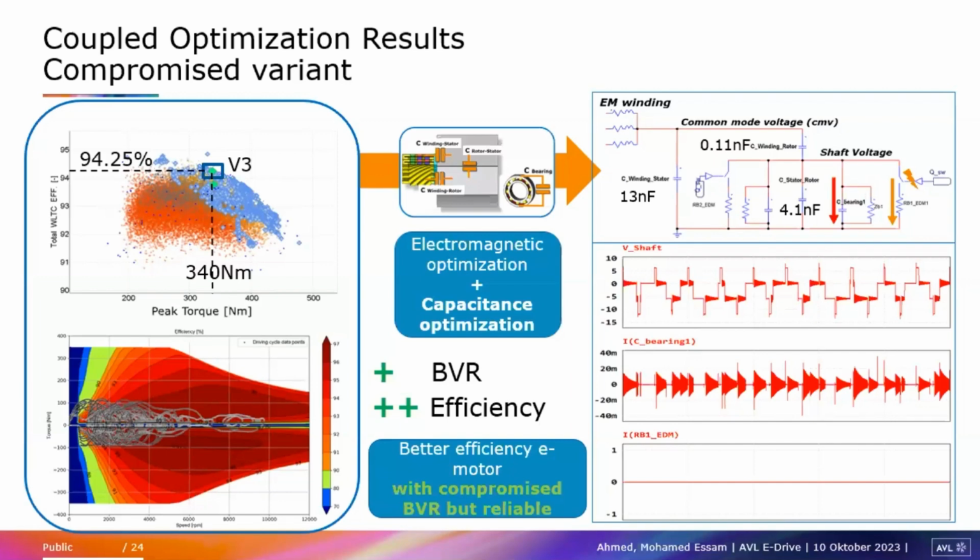All the solutions basically use something very small, a parallel resistance, either, as you mentioned, the ground shaft, or auxiliary bearings that are short-circuited. There are also some solutions with an inner shaft inside the shaft, which is also a parallel small resistance that can take this current, which doesn't go here, but goes through this auxiliary system. But it comes with cost.